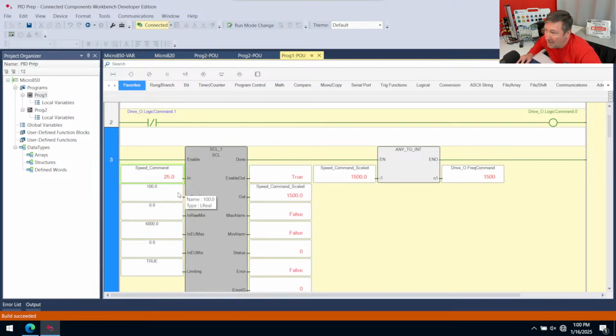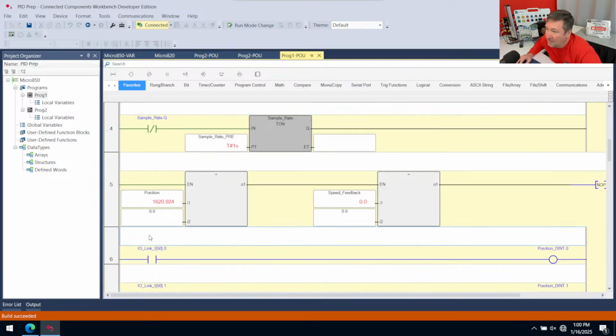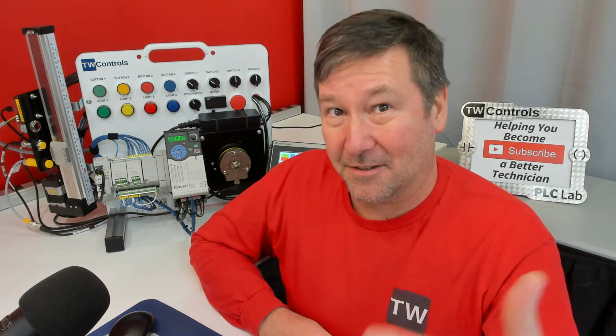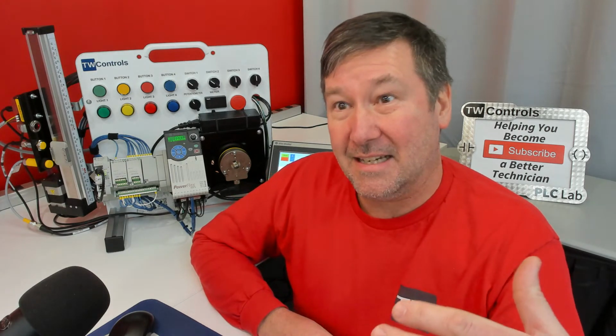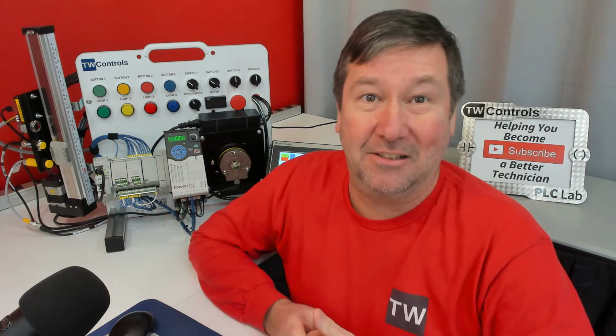So we have a speed command that we can give the drive, and then we have our feedback speed right here. If I switch forward to the left, that gets the motor starting to run, and that gets us some feedback going on. So we arguably are ready to set up our PID now and learn how to auto tune it. But along with that, we're probably going to need to see a graphical interface or a trend of what this data looks like.